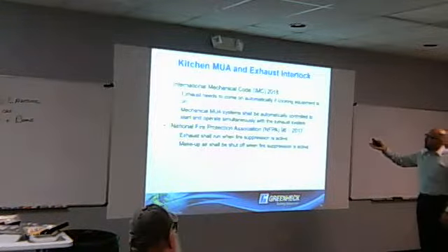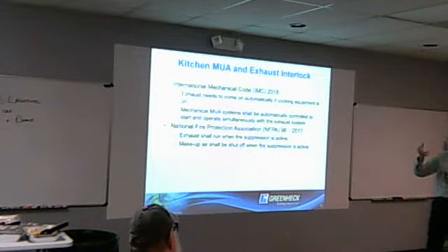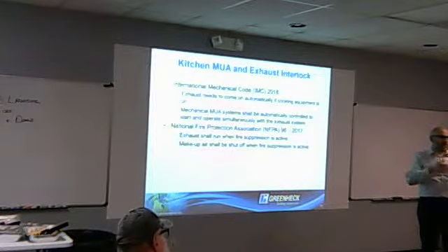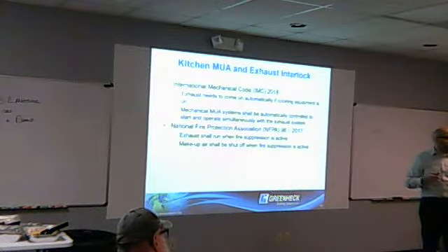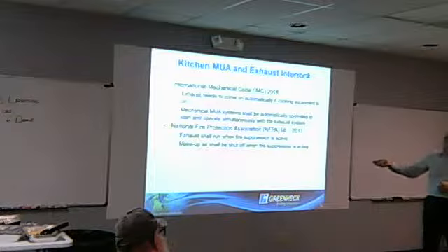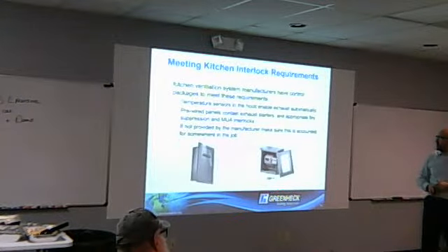The International Mechanical Code talks about if they sense heat, the exhaust fan needs to come on. If you're cooking, the exhaust fan needs to come on. There has to be an interlock between those two. But at the same point, if you're going to start sucking air out of the building, bring on the makeup air, so we'll interlock those two. NFPA, I just mentioned, the exhaust fan coming on, the makeup air shutting off.